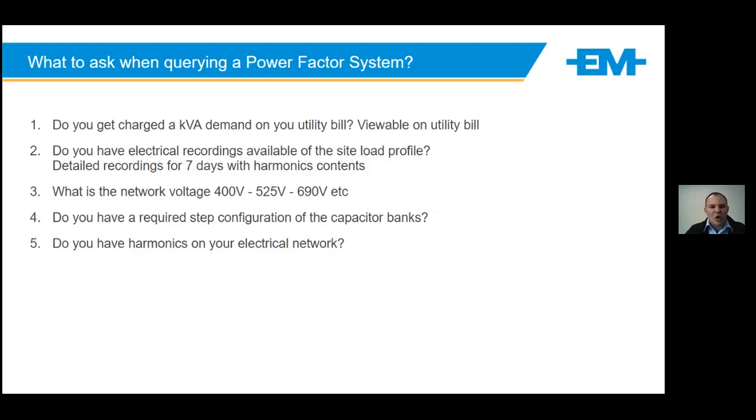The next question is, do you have electrical recordings available for the site, the load profile? Preferably detailed recordings with at least 7 days' worth of data, and harmonic content, which we'll get to. Another important question is, what is your network voltage? 400, 525, 690.